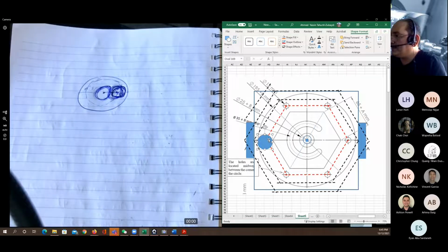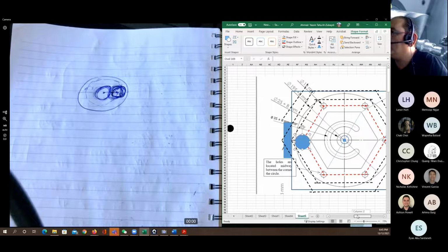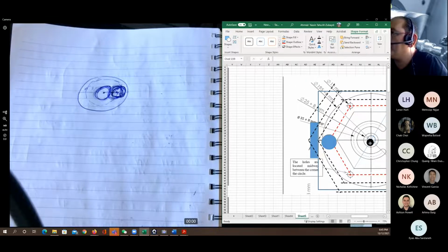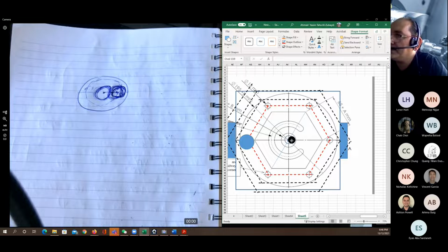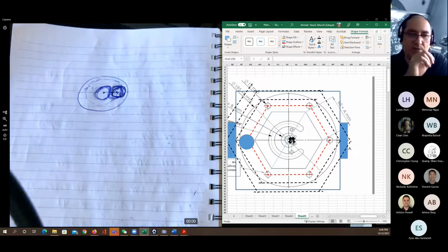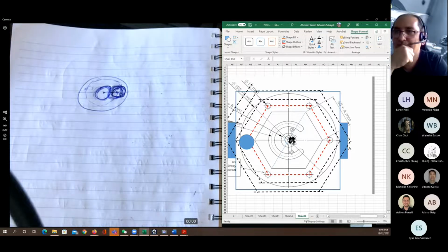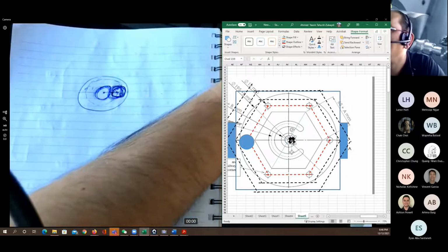Well, I think I need to show you that, yeah, we can do it here. Where's the small cutting tool? So we can bring the cutting tool to the middle, drill the hole, which is going to be 12 millimeters. Then we push it to the side, then make a full turn with the cutting tool, and it's going to clean the place. Did you get this point, or do you still need some explanation? Because I can do some explanation.